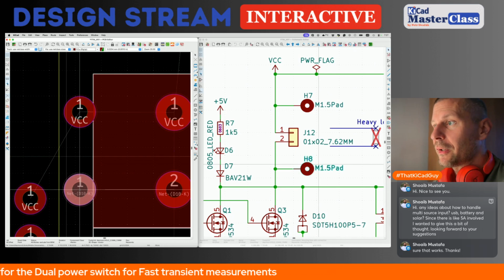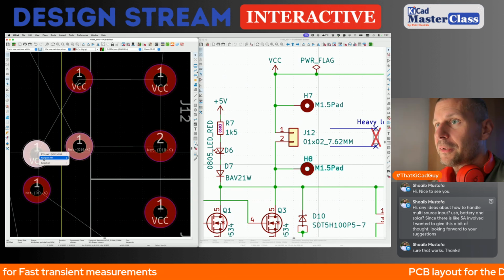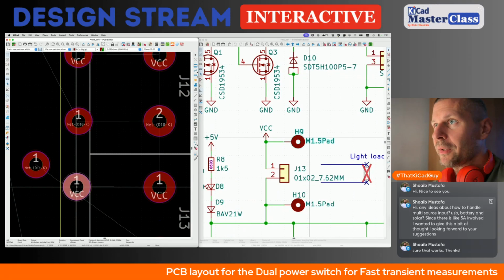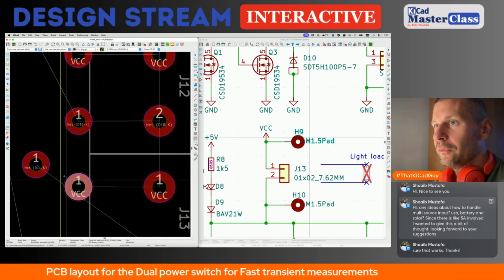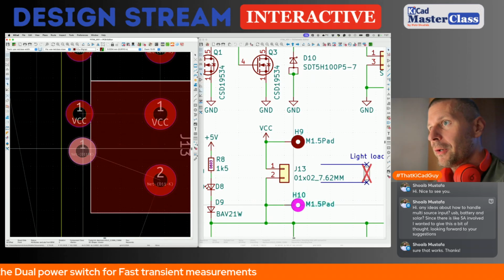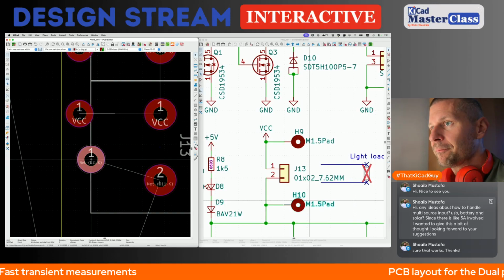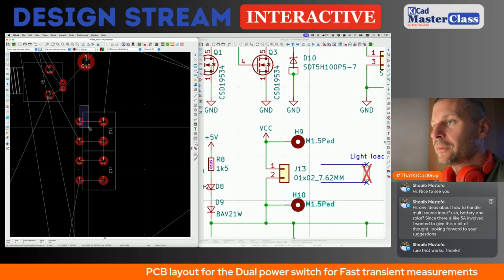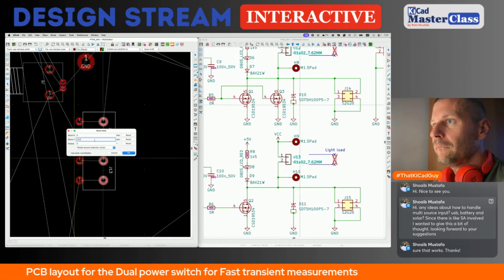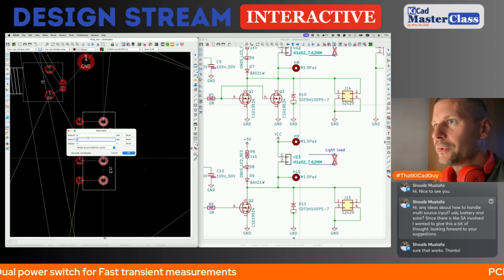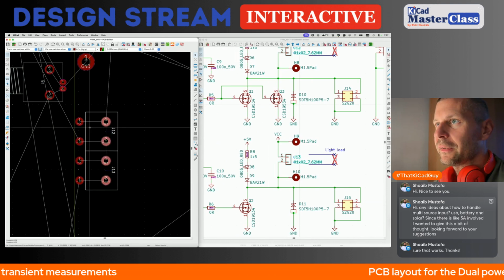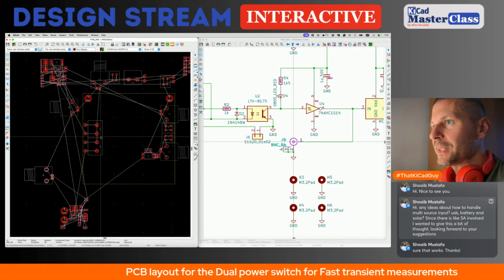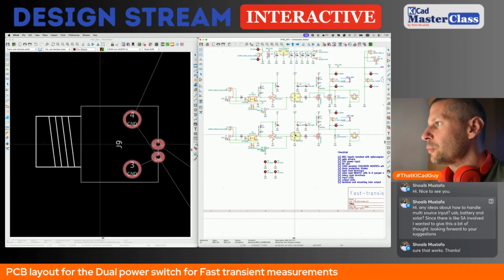Obviously, there are some courtyard issues with the footprints, but I will solve it by moving the terminals far from the edge of the PCB. Now I'm preparing the situation for the terminals and to see how much space will be there for the MOSFETs, etc. So these two terminals can be moved like 1 millimeter farther from the edge, yes, like this. Exactly. Now we said that this is the input 2.